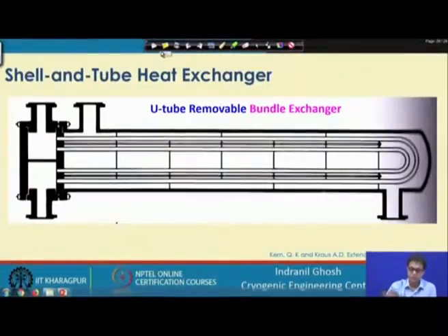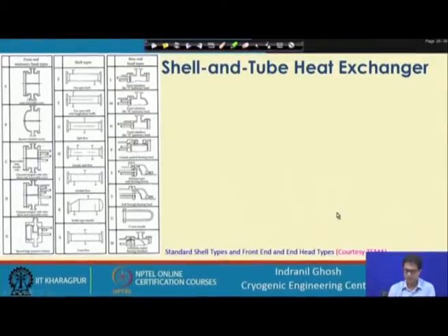So, now if we go to the other type, you will find the standard shell and the front and rear head types, and they are already specified. As I have told, the Tubular Exchanger Manufacturers Association or TEMA has given so many standards, and according to that standard we have different types of front stationary heads, and then we have the rear stationary heads and the shell types.